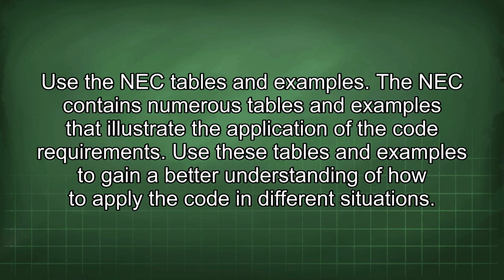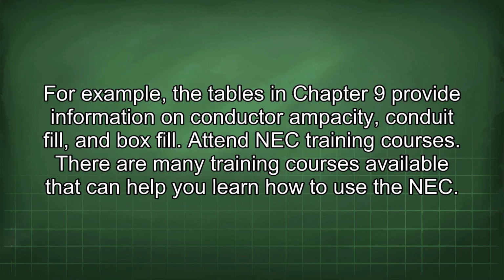Use the NEC tables and examples. The NEC contains numerous tables and examples that illustrate the application of the code requirements. Use these tables and examples to gain a better understanding of how to apply the code in different situations. For example, the tables in Chapter 9 provide information on conductor ampacity, conduit fill, and box fill.